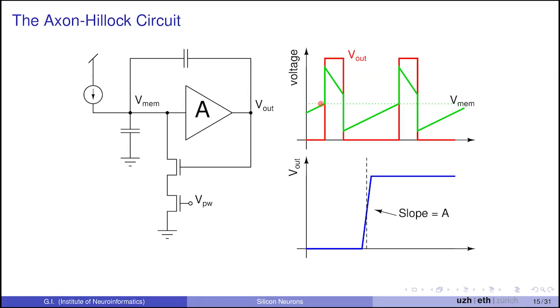Now, this plot here is showing what could happen if you have the up threshold different from the down threshold. So if your amplifier has mismatch, or the thresholds for turning on are different from the thresholds for turning off, you would have this condition. Otherwise, the green trace would go all the way back to the dotted line.